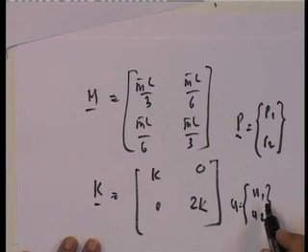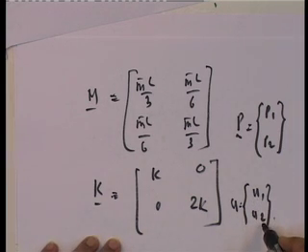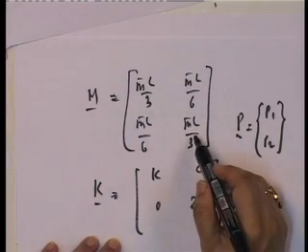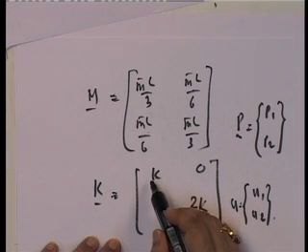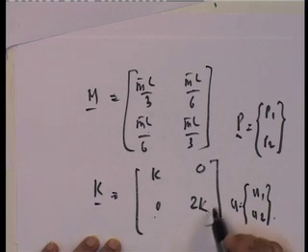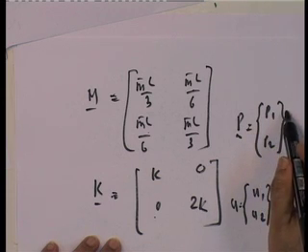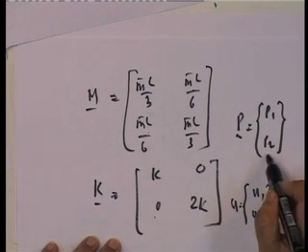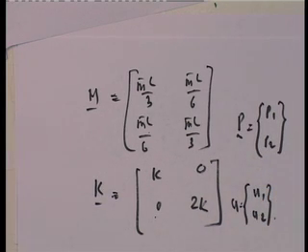When I defined it at the geometric center with ux and u theta, I got m bar L cubed by 12, 0, 0, and I got 3k, kL by 2, kL by 2, 3kL squared by 4, and p's were p1 plus p2, and the other one was minus p1 L by 2 plus p2 L by 2, completely different. But what does that mean? Does that mean that these are two completely different equations of motion?